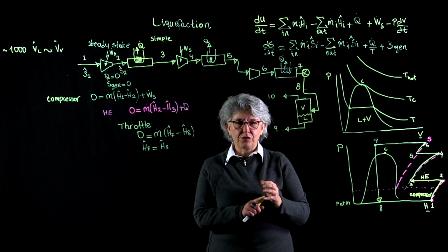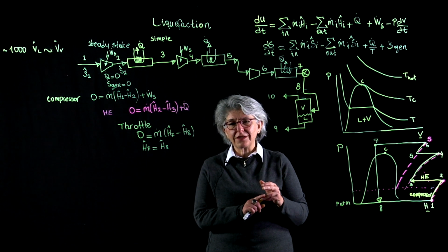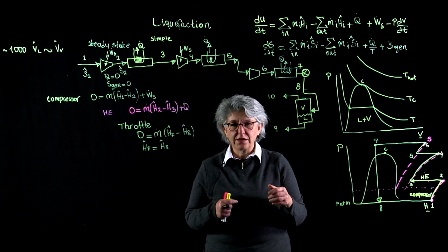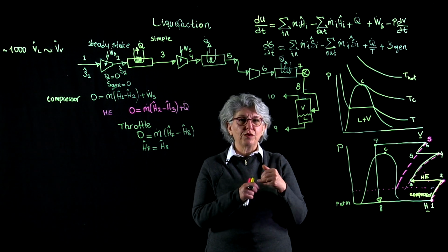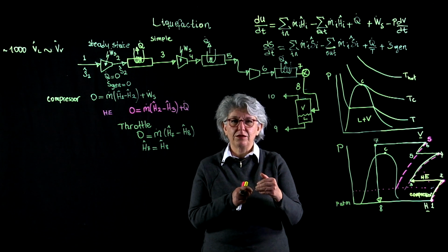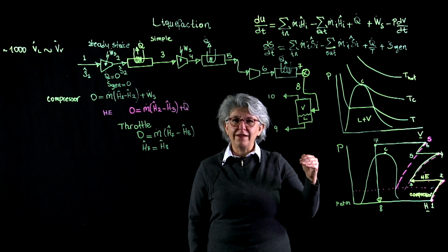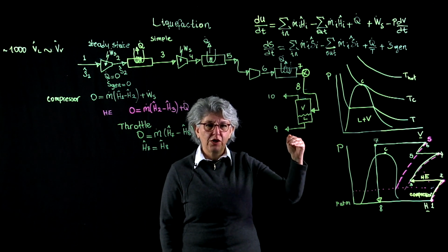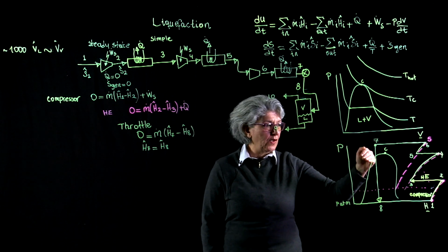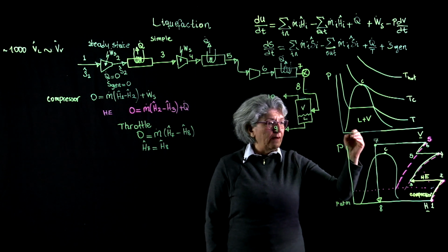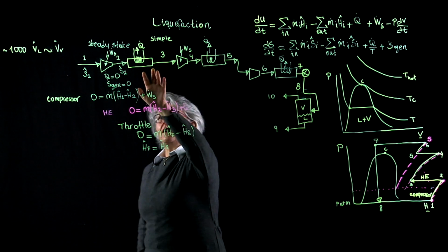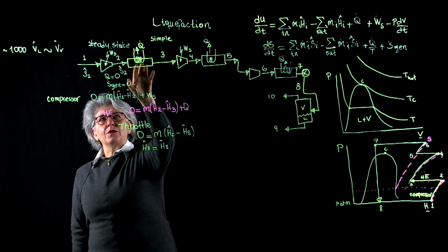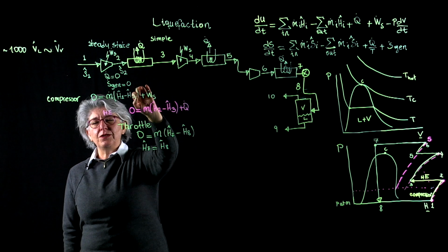And this temperature increase has to be checked, has to be controlled. The material of the construction, because those compressors need lubrication fluids, the resistance of those lubrication fluids to those temperatures should be taken into consideration. So you have a technological limitation to how high the temperature should be. Number one. Number two, we shouldn't have very high volumes to heat exchange, right?